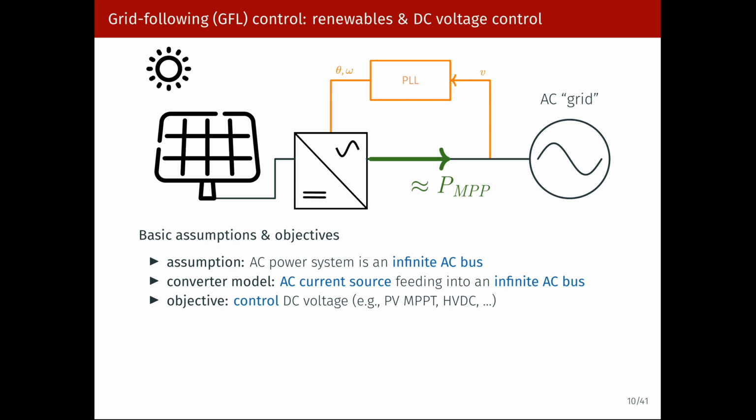And this is kind of a non-issue right now because, as I mentioned before, on those fast timescales, the response of a synchronous machine is mostly governed by its physics. I mean, there is no software there. There is not a software switch that someone can flip and change the response completely, but with a power converter, I can do that. So from that point of view, it's maybe not the implementation per se that's a problem, but how do you validate that the implementation is correct becomes very challenging.